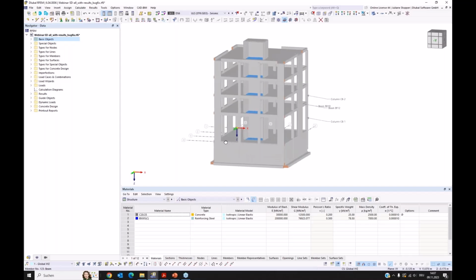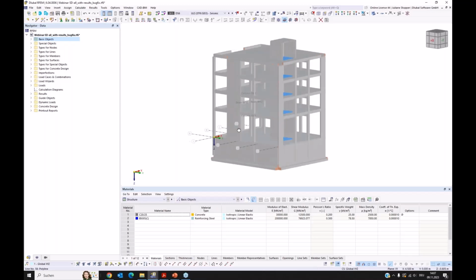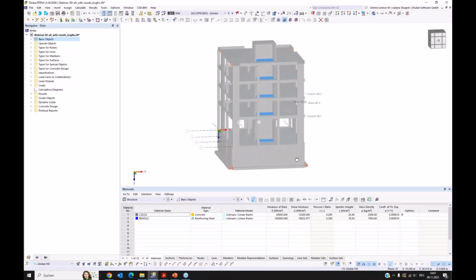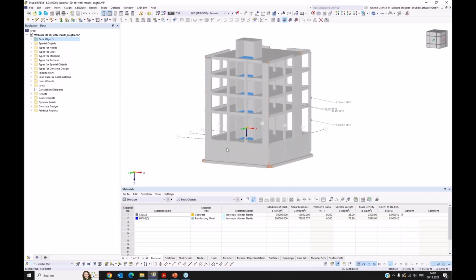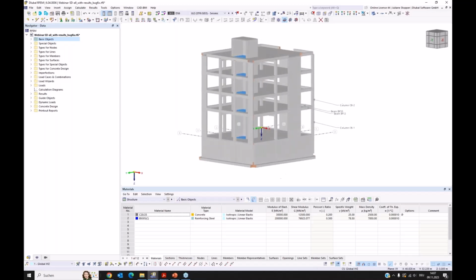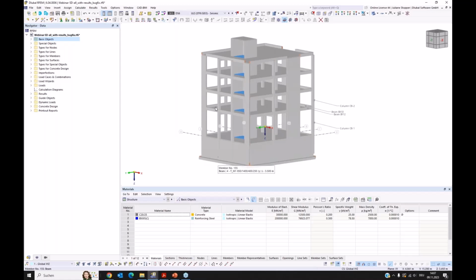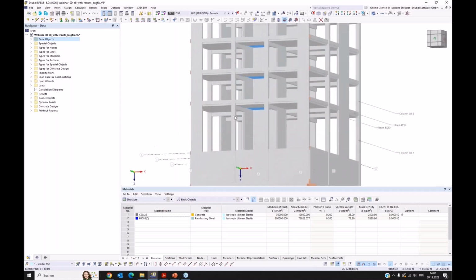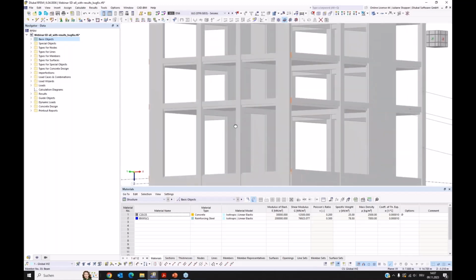and we have shear walls at every side, at least one, and we also have this U-shaped concrete core here in the center of the building, and we have columns that go from the bottom of the building up to the top continuously, and they have the same cross section along the whole height. And we have beams placed between all vertical members.